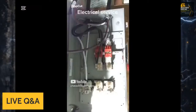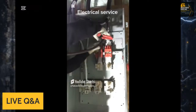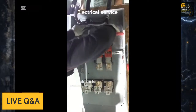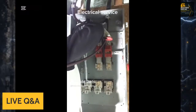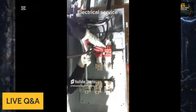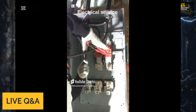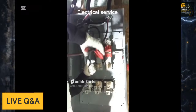Bonding is about fault clearing. Its job is to create a low impedance path back to the source, so overcurrent devices trip fast. Bonding connects metal parts and keeps everything at the same electrical potential. Bonding jumpers, equipment bonding conductors, bonding of enclosures, bonding screw, strap at service disconnect. OESC Rule 10-700, Rule 10-606.